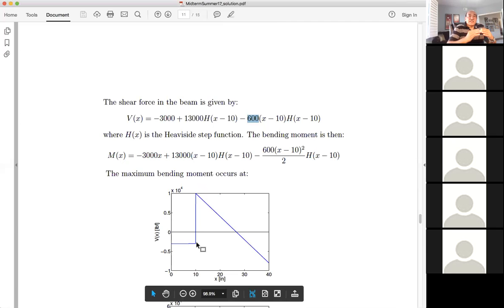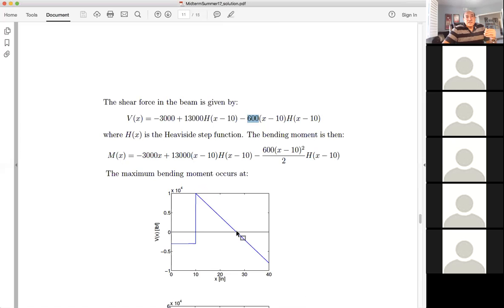So you would imagine a straight line, negative, and then a parabola coming out, and the parabola has a maximum. The maximum of the parabola is when the slope is 0, because the shear force has a 0 value here. So the 0 value corresponds to the maximum. I think several of you realized that, and that led to great simplification.